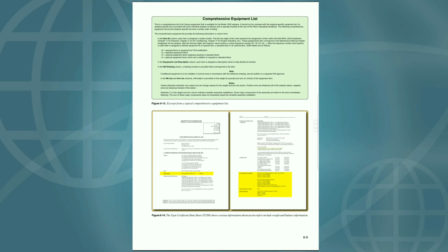Governor assembly: 1 Hartzell hydraulic governor, model F6-18A, right. 1 Hartzell hydraulic governor, model F6-18A, left. Avoid continuous operation between 2200 and 2400 RPM, unless aircraft is equipped with Hartzell propellers which incorporate a Hartzell damper on both left and right engine as noted above.